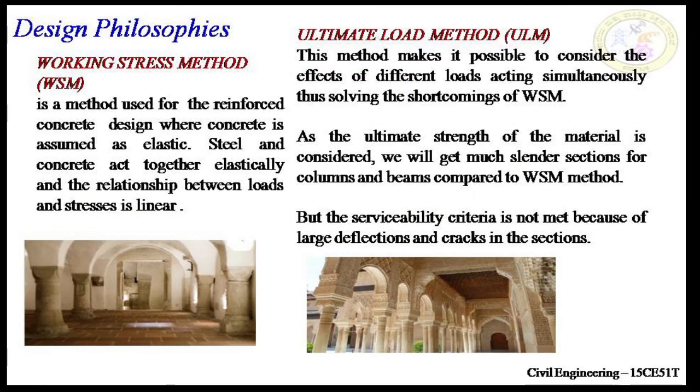Design philosophy. Coming to the present trend of practice, that is limit state method. Prior to this method, there were many other methods which were tried in practice, that is working stress method and ultimate load method. In working stress method, it is defined as a method used for reinforced concrete design where concrete is assumed as elastic. The assumption states that both steel and concrete act together elastically and the relationship between load and stresses are linear. However, in practice, this assumption is not true.